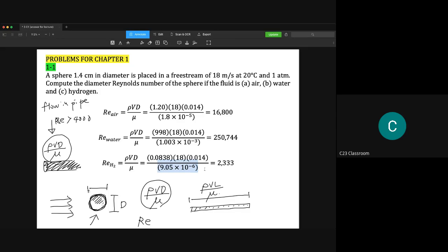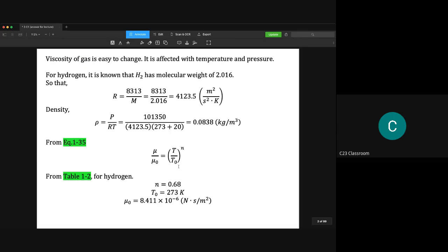So this is the first calculation, where we just use a common value for the dynamic viscosity of hydrogen. However, for the second method here, we are very specific. Normally, for example, we take the molecular weight of hydrogen as 2, but now we are very specific, we take 2.016, and then we calculate the density changes.